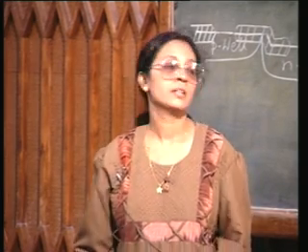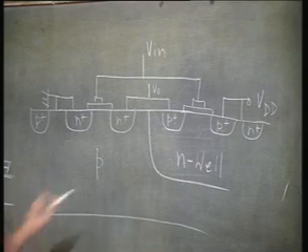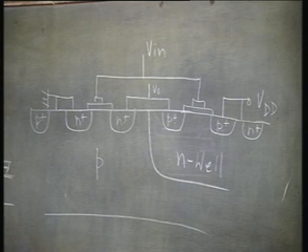Once this NPNP structure fires itself, even after the noise signal is removed, you can't really control it. So, latch-up is actually a major problem in CMOS.